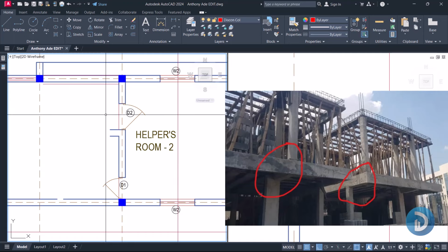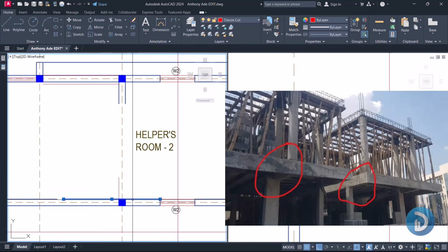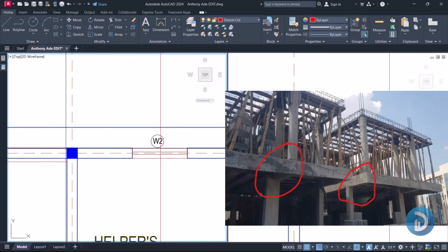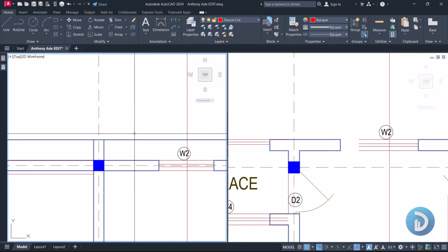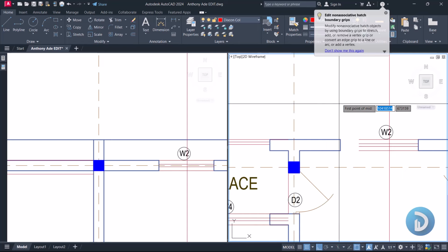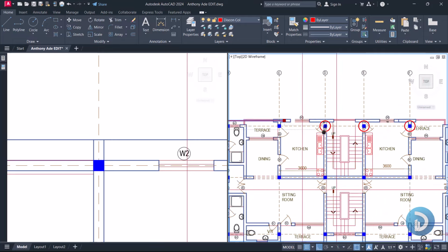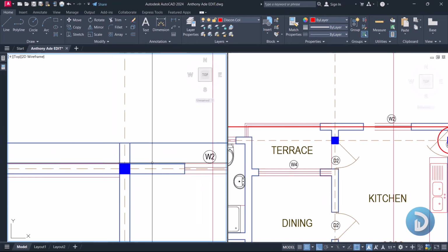Okay, so we'll cantilever this beam. When this beam is running from this grid line up to this point, it will have to cantilever till this edge. Okay, it will cantilever to this edge. So it is at this edge that this beam will be able to receive this column at the first floor. Okay, so we'll create a grid line here. We'll create a grid line in between this point. We'll create a grid line here, which is the same distance as here to this point.